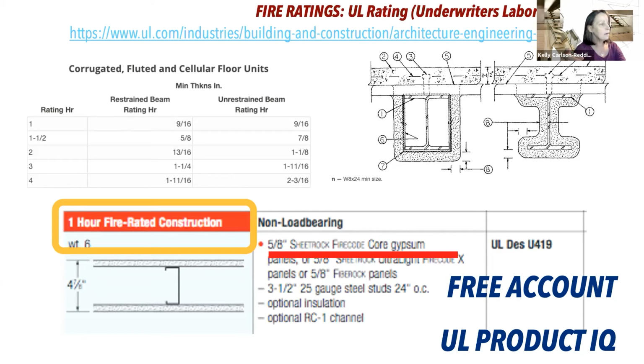On the right here is fire protected steel. And I typed in that I wanted fire protected steel with some kind of a spray foam insulation. And this diagram is basically accompanied by the amount of thickness of that insulation barrier to get me the fire rating. So for 3 hours, I would need 1¼ inches over here. So this is way more detailed than what you're doing right now. I just wanted to sort of show you where it goes in the long run.